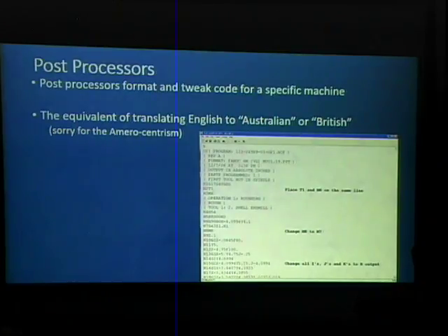It's going to do things like, if you see down here, on a circular command, the G02 and G03, you can call out the radius of your circle in two different ways. You can call it using an R. R allows us to call a specific radius, right? Simple radius. You can also call out a center location. That's basically forming an arc that moves about an arbitrary center that you define. Some machines prefer one method over the other. Some machines allow both. And there are certain advantages to using different ones that are going to be specific to your machine and your code and your use.